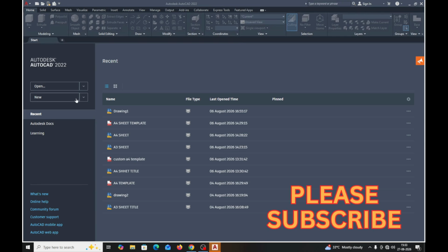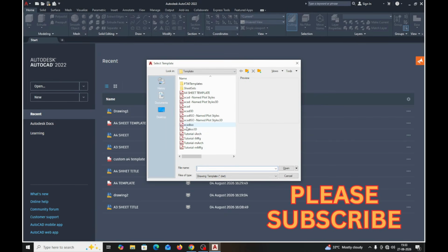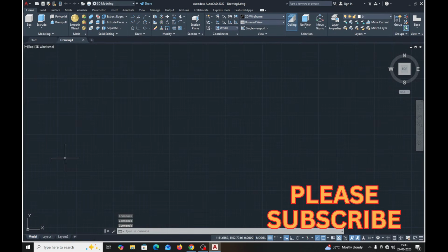From the new section on the left-hand side, if you want to work in the metric template, you can select ACAD ISO DWT, or for the imperial unit, you can select ACAD DWT. If you don't find this template, browse for a template. From here, you can select ACAD ISO and open it. Now this interface comes up.